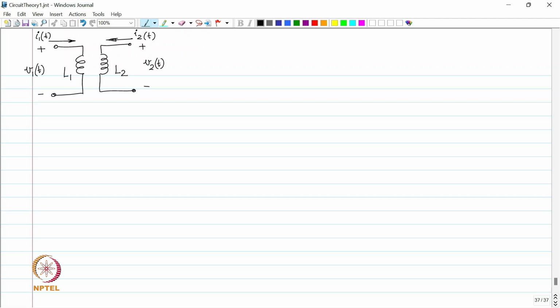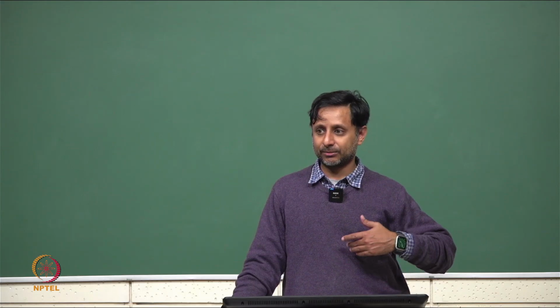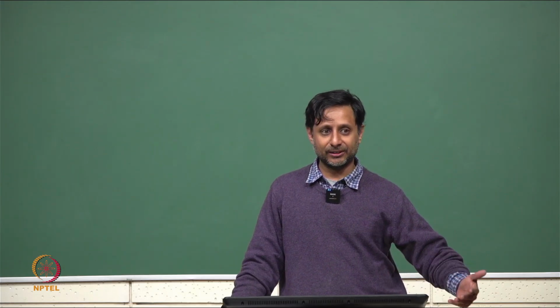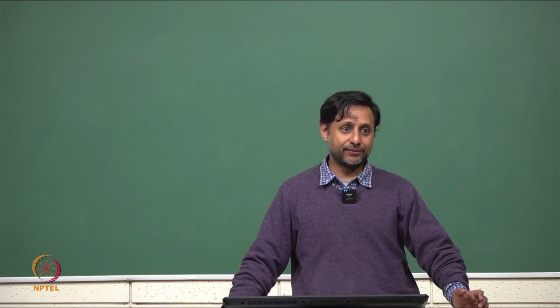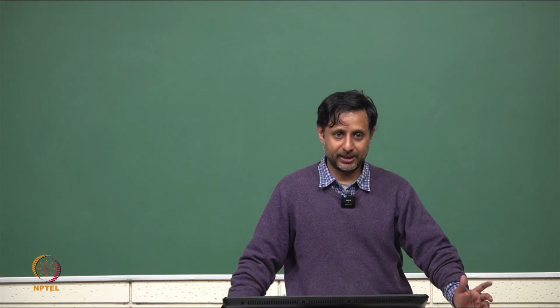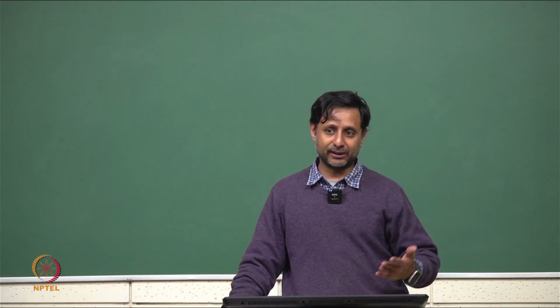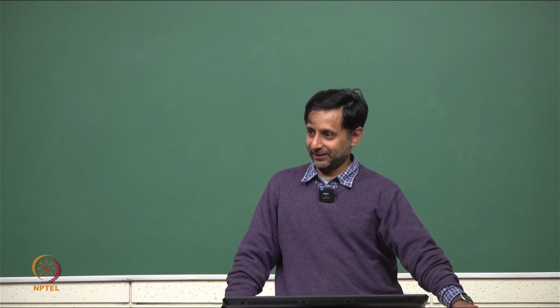When I have written everything in small letters, it means that we are working in the time domain. Sometimes we work in the time domain, sometimes we work with phasors, which are not in the time domain, they are in the frequency domain. You shift your perspective from time to frequency.